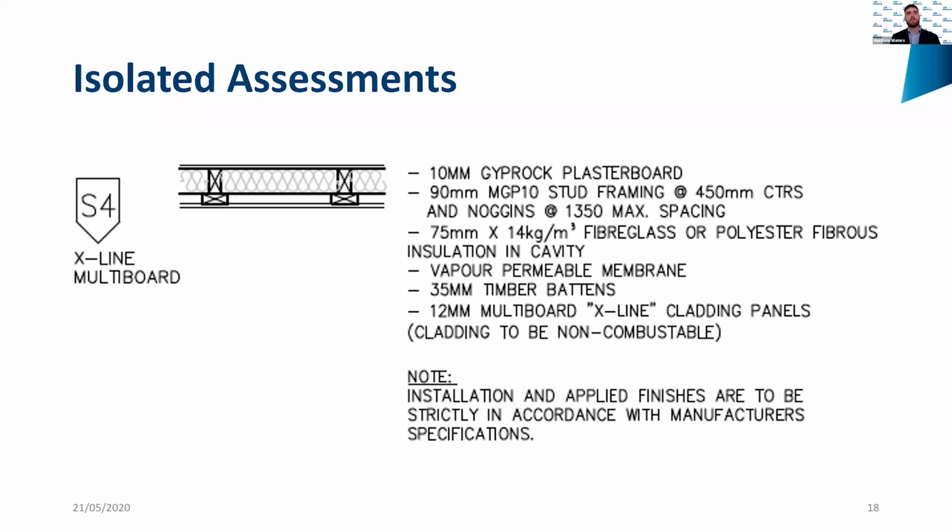This is really something that we commonly see in audits where something very specific is identified and then a performance solution addresses it, but it fails to consider the wider holistic compliance and all relevant performance requirements. To this effect, the requirements of the BCA are built on redundancies, and many of the performance solutions we see remove these, and then they leave no protection in place if active system failure was to occur, or if there were poor construction practices on site. So it's really important to look at the BCA holistically and ensure that all relevant performance requirements are being satisfied.